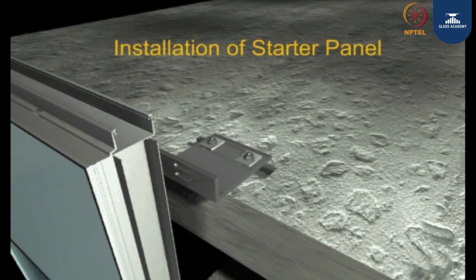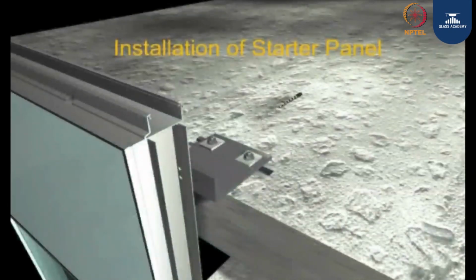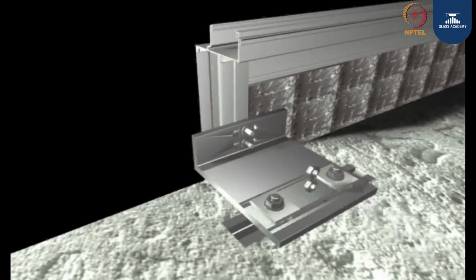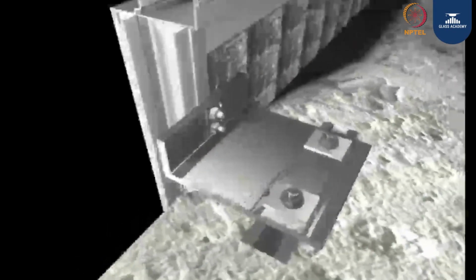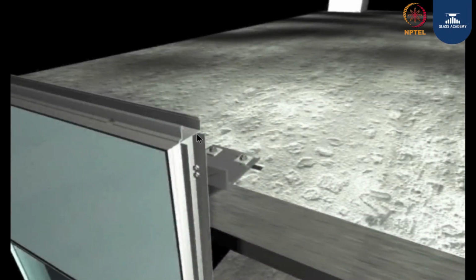Now, the panel comes from factory fully done. You put them there and you drill 2 bolts. It is a simple form of fixing the system. So, you see you put 2 bolts, you attach them, you are done, that is it. The panel is installed. What you see here, this is a gutter head, what we saw as the split mullion, it happens slightly above the floor level. This is a mullion waiting to receive the other panel. So, the stack joint, now you have the head portion of the panel.